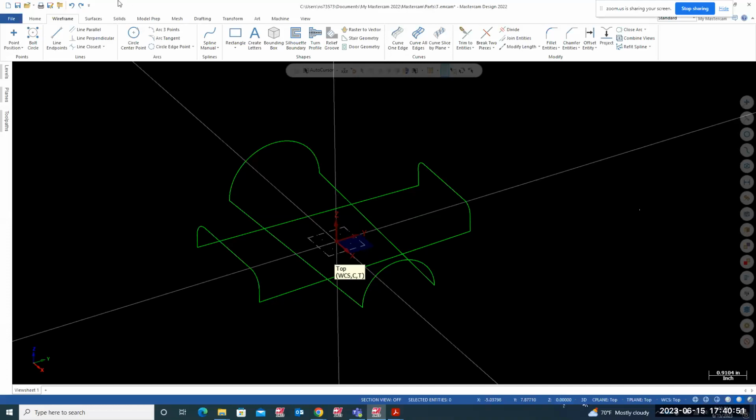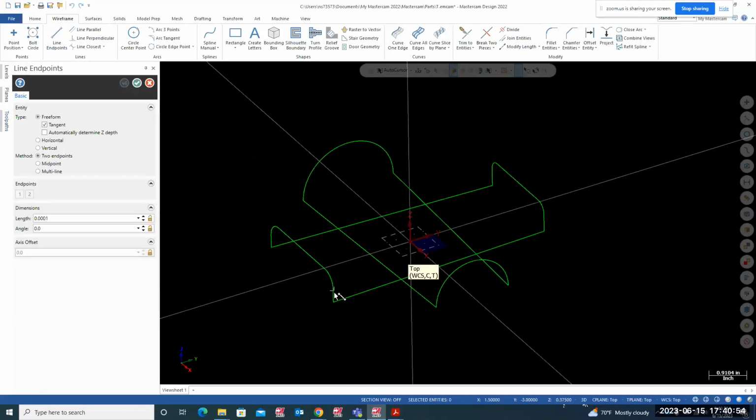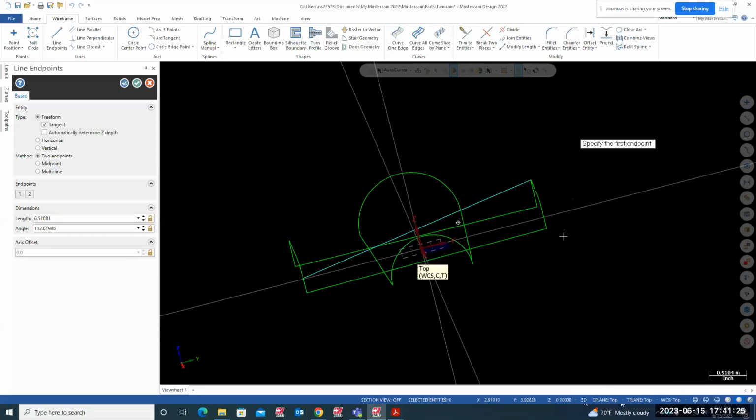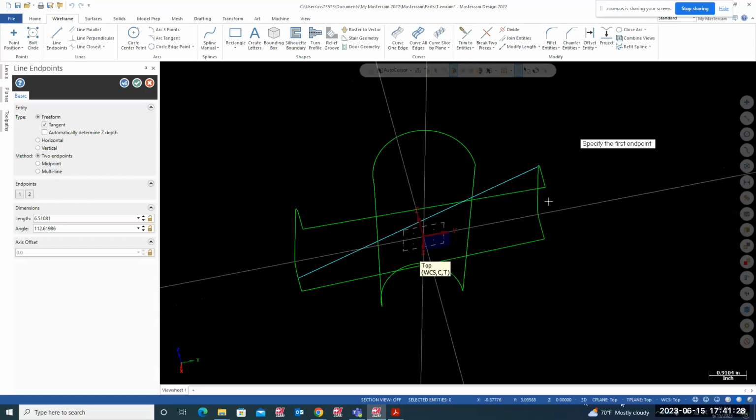So if I'm in 3D, watch here, I'm going to say line. I want to start a line from here. Perfect, no problem. That's my 3D, X, Y, Z. Whatever X, Y, Z you see over here at this point is where I'm going to start my arc. If you read those numbers over here, X, Y, Z, guys, look at this. X is 1.5, Y is -3, and Z is 0.375. Okay, perfect, because we are in 3D. So wherever I click, I want to click right here. There we go. That's your line right there. It's in 3D. So over here, your Z is 750.